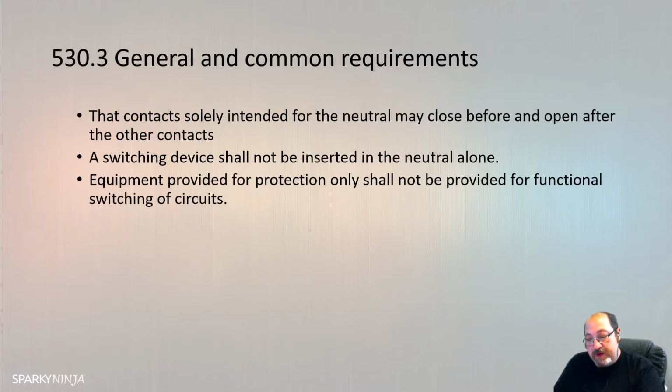Devices embodying more than one function as defined in the regulations will comply with the requirements for the chapter appropriate for each separate function. So if a device achieves isolation and protection, it must comply with the requirements of both isolation and protection, and one must not inhibit or affect the other.